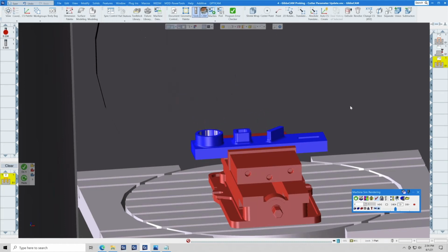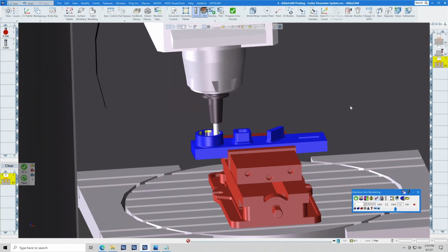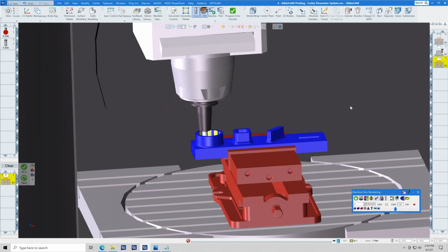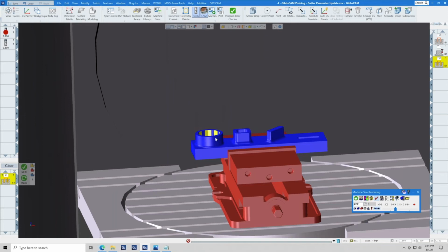Cut, measure, update the tool, and then bring the tool back in and cut that part to final size with as tight a tolerance as we can get. Here's something that we have found out through practical application among our customers: by using this method, if you have a machine capability of 4 10,000ths, we have found that you can generally hold that capability or just a tiny bit inside, maybe 1 or 1.5 tenths inside, by using this method.